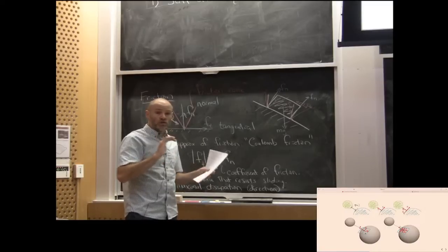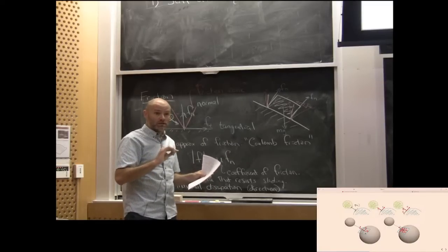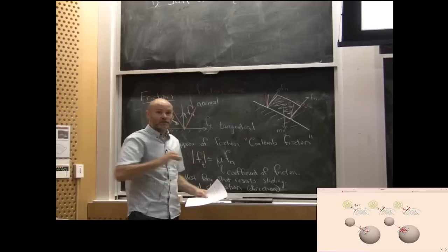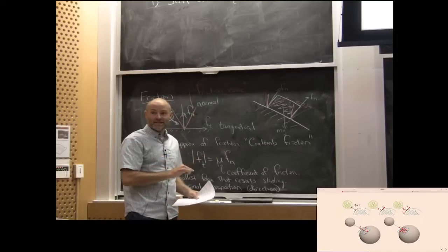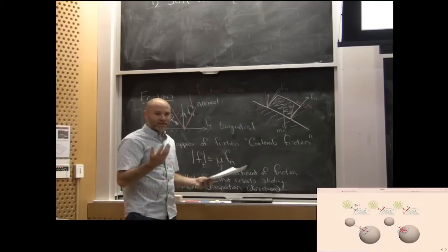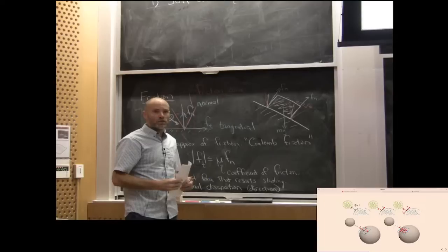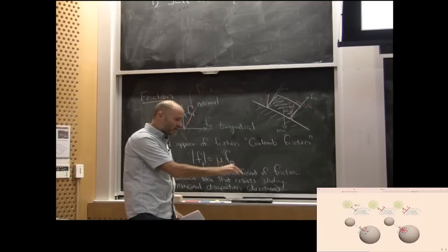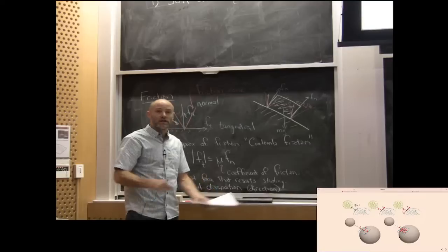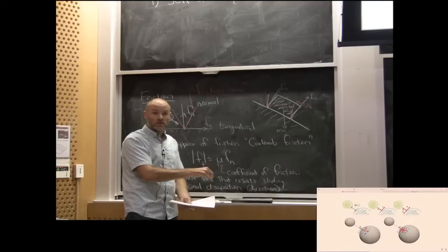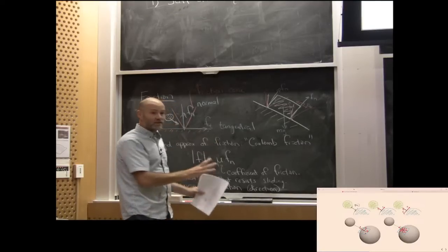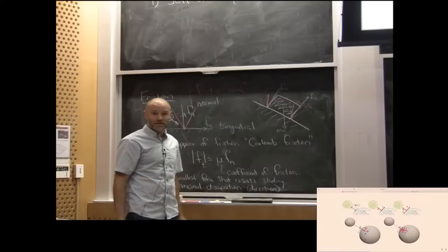That means that the rules of mechanics don't actually tell me how much normal force is in each foot. It's just a failing of our rules of rigid mechanics. I could take some normal force over here and put it over here and still get a valid solution to the equations. Everything I've said here does not completely define what Fn is.